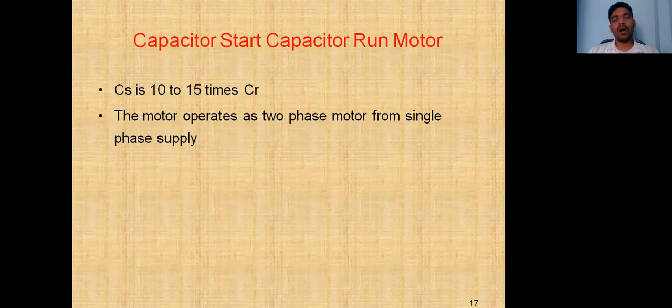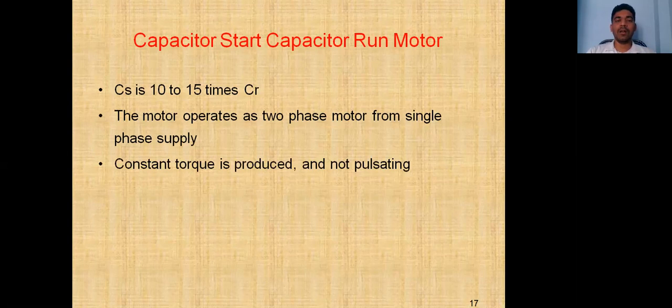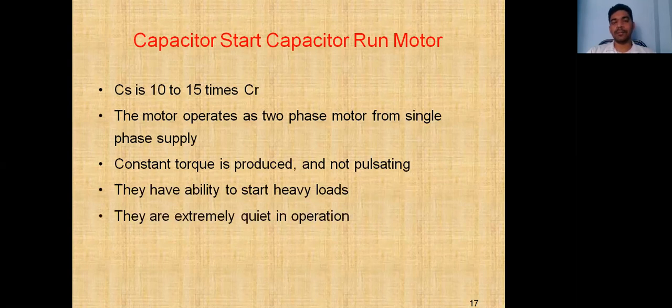The motor operates as a two-phase motor from a single-phase supply. Constant torque is produced and not pulsating torque. They have the ability to start heavy loads.